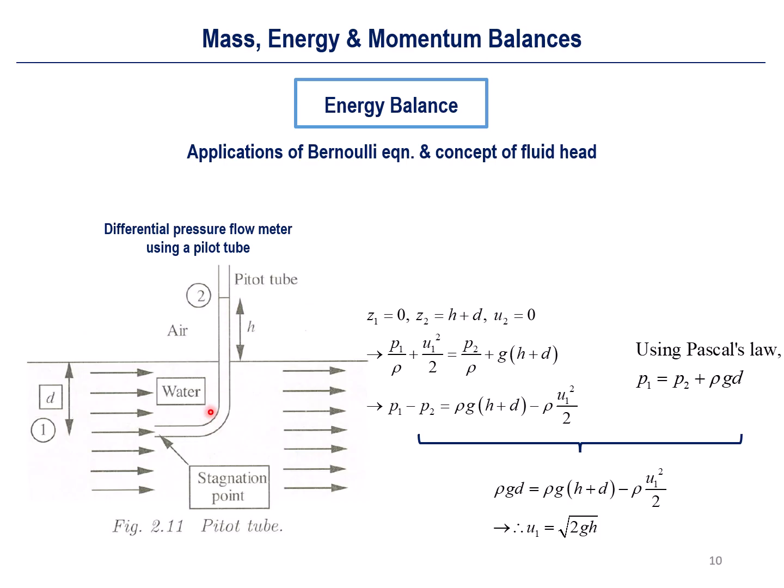This is very narrowed down, and we are witnessing some spontaneous increase of the liquid inside of this pitot tube, and this pitot tube can be approximated as a type of system with point number 1 and point number 2. At point number 1, the velocity U1 is 0, and we measure this relative height change, which is h plus d, and at point 2 there is no movement of the fluid, so U2 is 0.